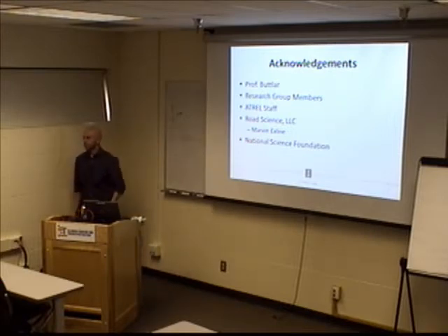But there's a lot of work to do in the meanwhile, because if you just buy a DIC system, there are a couple of companies that market them, they'll do a fine job for homogeneous materials and strain. They struggle with heterogeneous materials and strain, and they're almost useless for heterogeneous materials in fracture. They don't identify cracks, they don't analyze cracking fields properly. So Brian has his work cut out to do that, and to work with the modelers in our group to integrate the two pieces. Go ahead, Matthew.